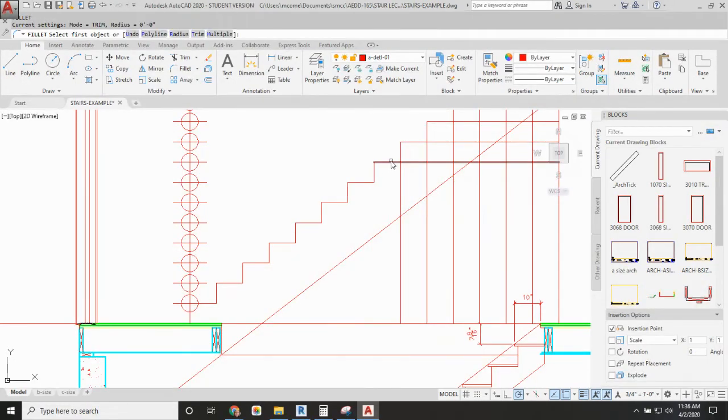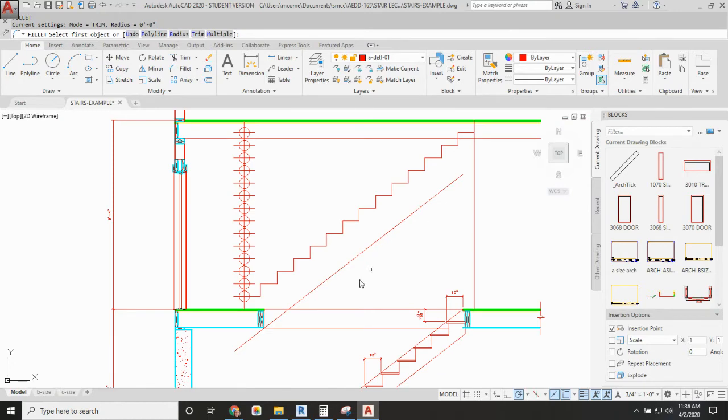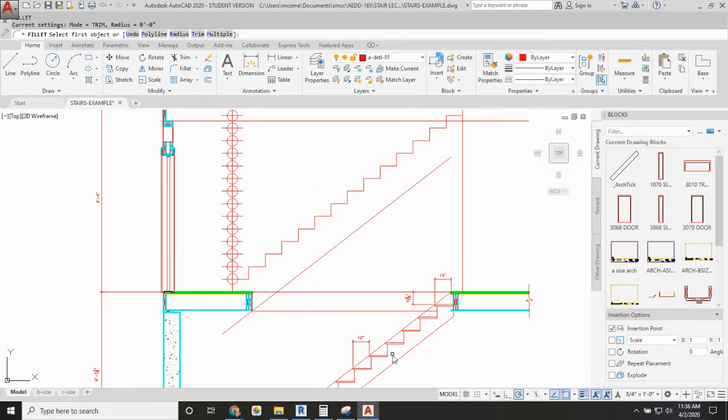you'll see that the stairs are not coming out exactly the same because we had different riser, total rise heights. I had a total rise of 9 feet 4 inches on the first floor to second floor. So these stairs that are being designed for this level are a different rise and run ratio than the ones to the basement. So to create that stringer, go from nosing to nosing, offset 11 1/4,